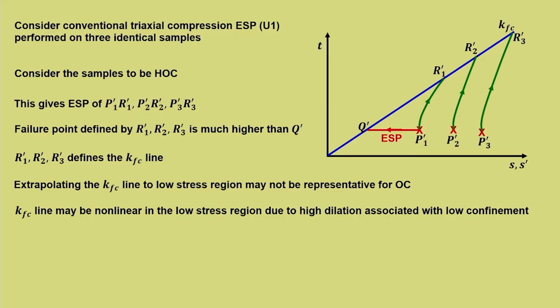So, you may naturally have a question that okay, we are working with a higher strength, then how do we get an appropriate result? Now, in any kind of work which we execute on a given slope, we always have a higher factor of safety, we take a factor of safety margin. So, it is mainly because of that, and please understand we are not dealing with a man-made slope.